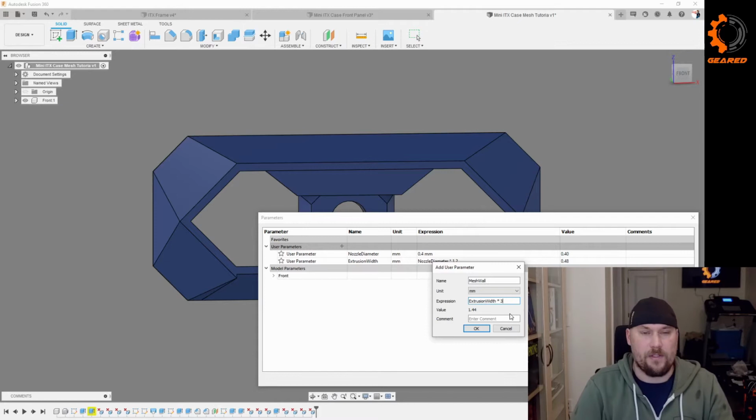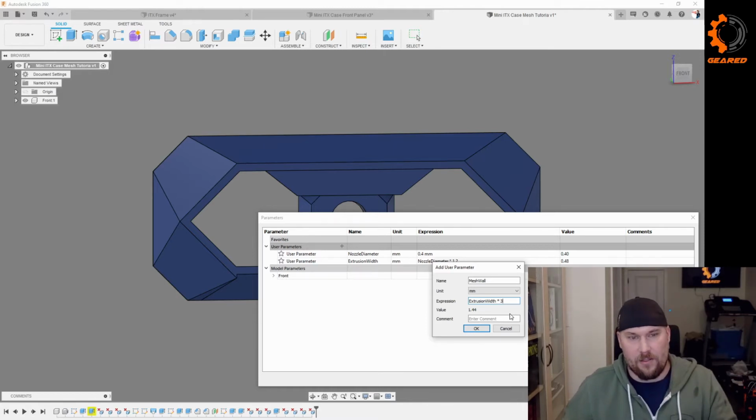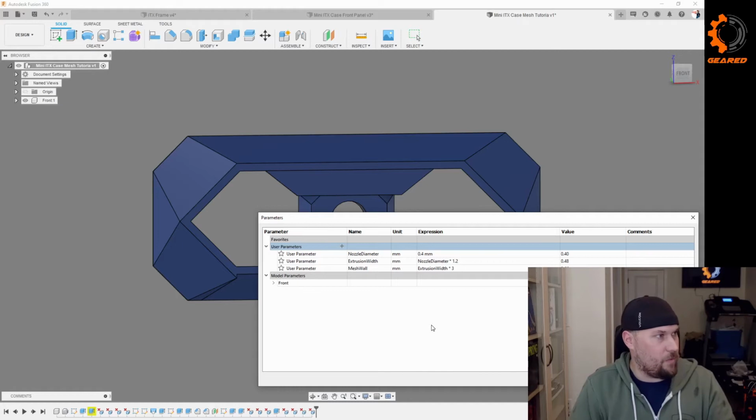And the reason we're doing this is to make it easier for the slicer and the printer to print out the lines of the extrusion, or excuse me, of the mesh width without having to compress or dynamically try to change the width of that extrusion. It also keeps it from creating gaps inside that extrusion. So this will make a nice, solid 3 lines of extrusion for those walls. And we can also come back and add extrusions in there if we want to make it thicker.